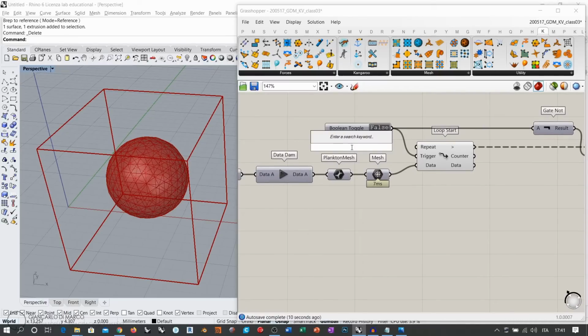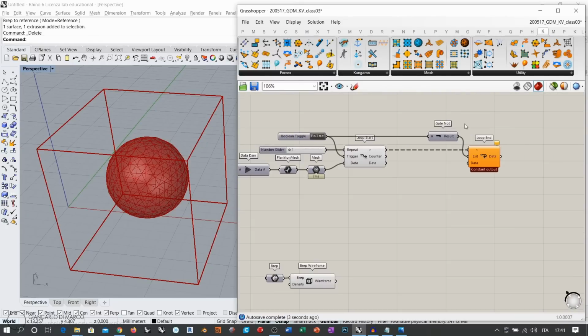Now the number of repetitions, in this particular case, I normally suggest to keep the number of repetitions low when programming a loop. Particularly with mesh growth, I would suggest that this slider should not exceed, for example, 5 repetitions, which is already a good number. So I would say eventually from 1 to 5, and I will keep it to 1 right now. So I want this loop to perform just 1 iteration.